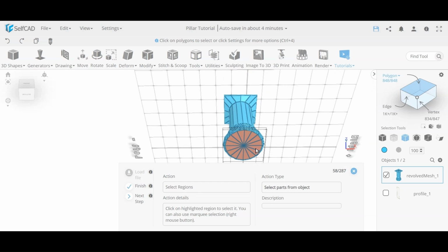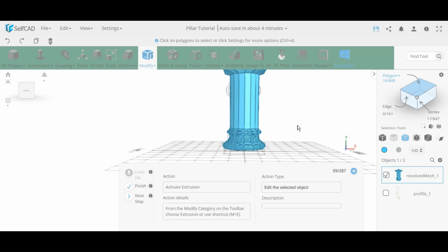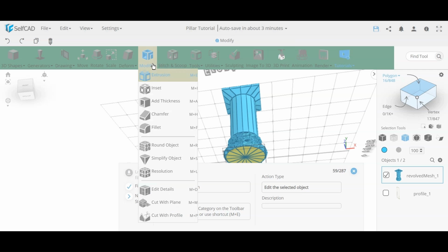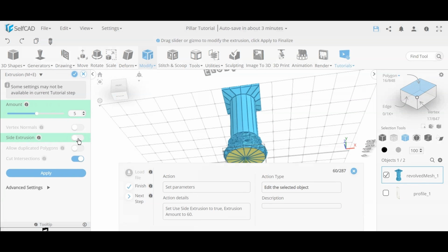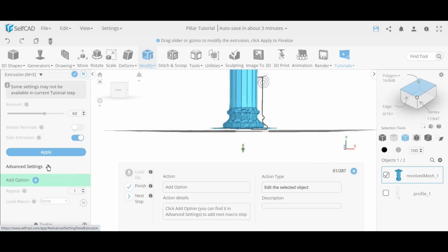So now we're going to do the same thing at the bottom. We didn't do this in one shot. You can technically do them together, but it's going to be a slightly different style, because the bottom is not going to have this angle over here. So we're going to use about the same approach, same concept, which is going to set this to 6D and use inside extrusion. But now instead of moving it, let's see what we do over here.